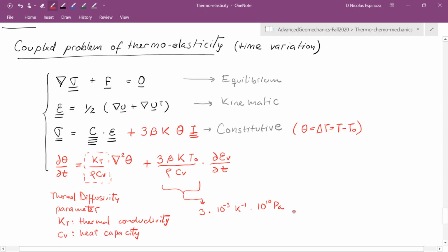And for the initial temperature, we'll assume that we are near surface conditions. So here I'm going to use 300 Kelvin. For density, I'm going to use here the density times the heat capacity. I'm just going to use one number, and it's going to be 1.76 times 10 to the 6 joules per meter cube times Kelvin.